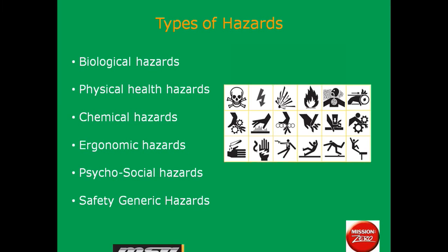What about physical hazards, such as the noise levels? How much noise is that worker exposed to? The decibel level. Or vibration. Our association teamed up on a study where we measured vibration levels in impact wrenches, and we recognized the hazard of the vibration and the control of using a Sorbothane wrap to wrap that impact wrench to reduce the vibration level that the worker is exposed to. So that's an example of a hazard and a control. What about the light? Is lighting an issue? Is it too dark that the worker can't see?